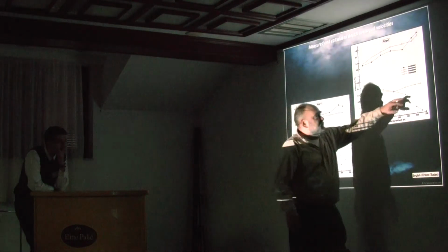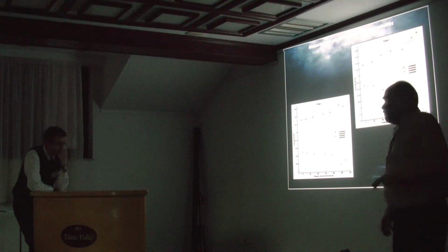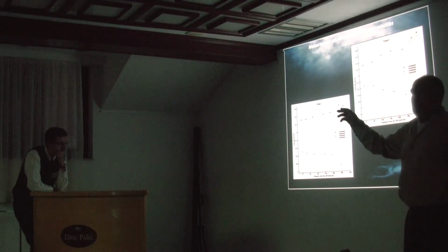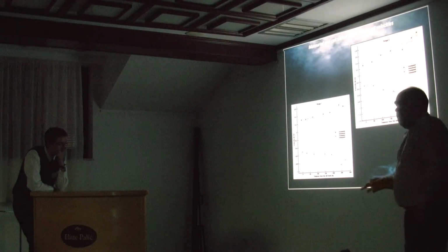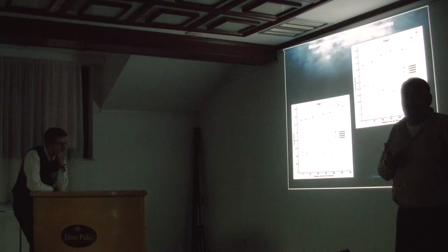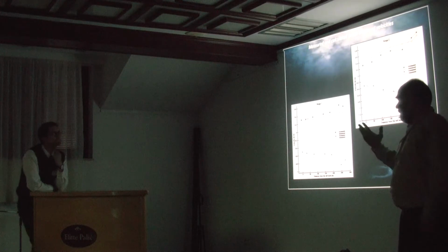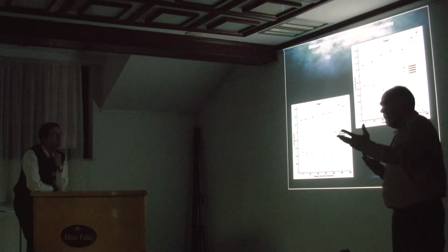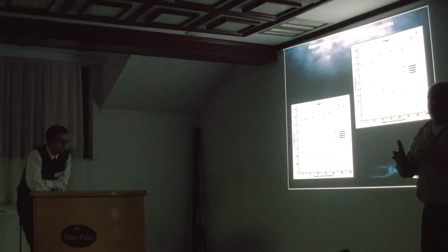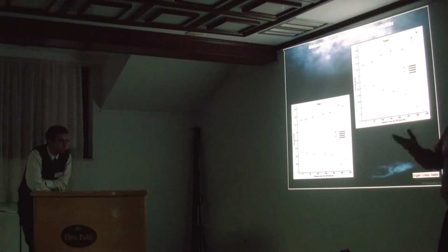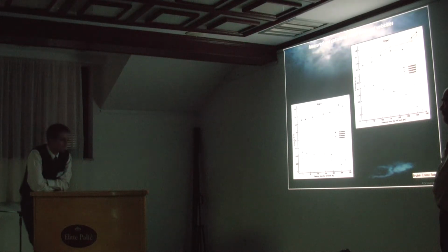You'll see the rest of them. This one is the worst thing. We are not sure what happened. We know that at that cross section there was not only 7 verticals that were shown here, there were 2 additional ones. So there was 9 velocity verticals and 2 additional ones were showing 0 velocities or something like that. So this may require taking a closer look, trying to find out if that was something around the structure behind the dike or whatever.